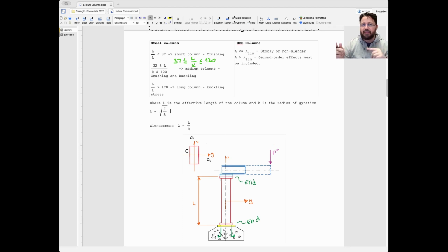Right now, it's hard for me to answer why they wanted to do that, but I took it for granted. If I wanted to simulate the mass distribution of this area around these two axes, for example, if I take this y-axis, the mass distribution of this area is going to be this one. If I take this axis, it's going to be these two. But if I want to simulate the mass distribution of that area as a particle, then that mass distribution is equivalent to having a particle at a certain distance from the center of the Cartesian coordinate system. And that distance is called the radius of gyration.